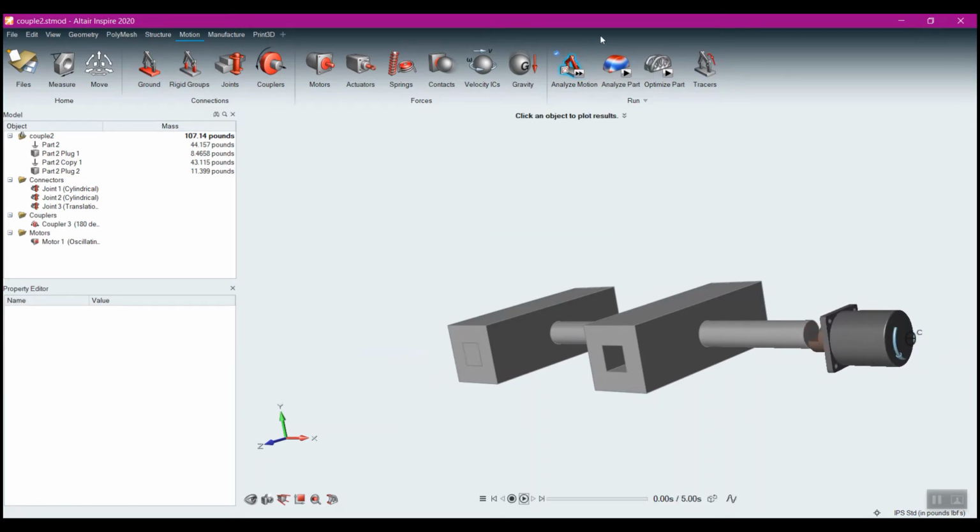Essentially, all you're doing is saying the behavior of one joint is going to be coupled to the behavior of another joint through this scaling factor, through this ratio. So you can imagine, if I had gears, I could set the rotation of one gear joint to be 360 degrees, and the rotation for the other gear joint to be 720 degrees, and effectively that would be a 2 times gear ratio.